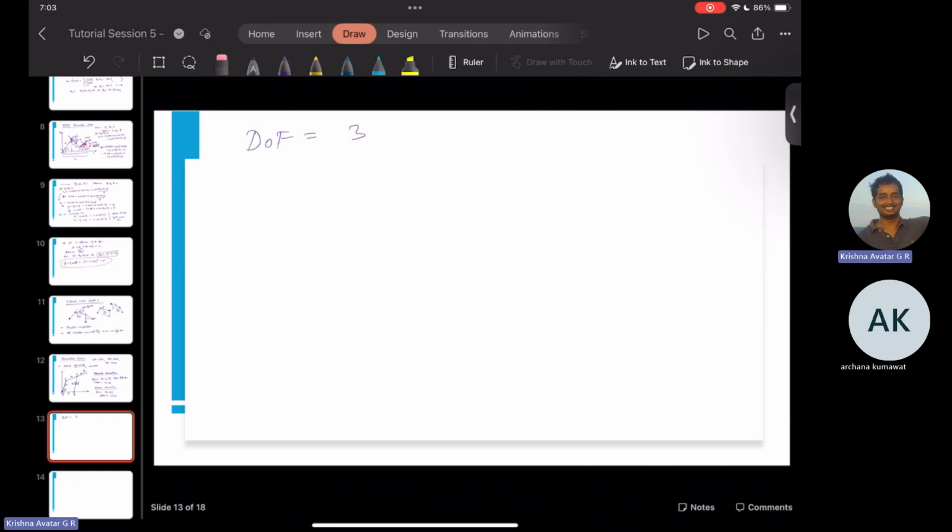And then there is another set of closed chain planar robots, for which we have two types, 3 into 3R, and which was discussed during the class, 3 into RPR. The kinematic diagrams for 3 RPR, or maybe we can start with 3R. So in this case here, it implies that we have 3 into 3R. So that is what it means.